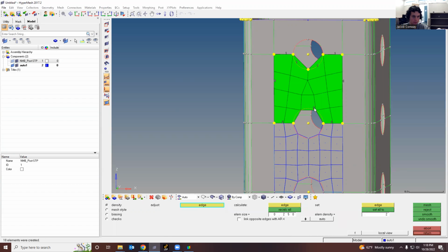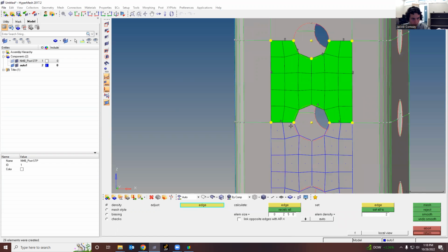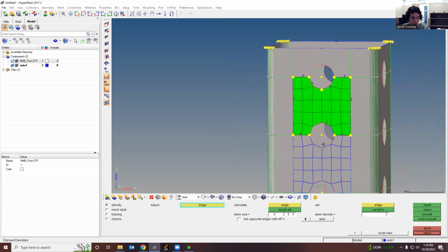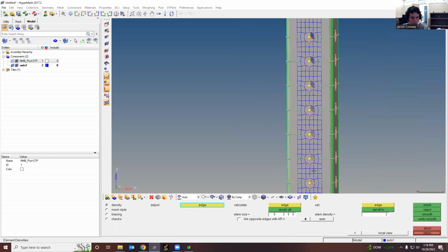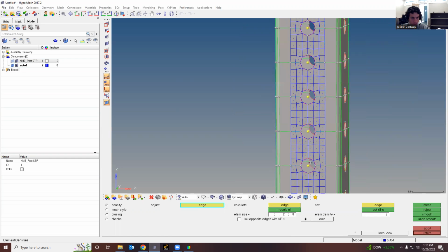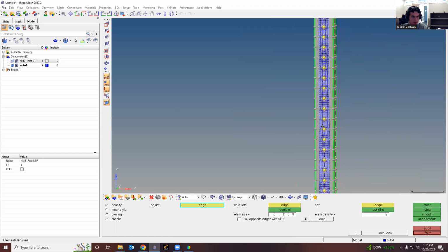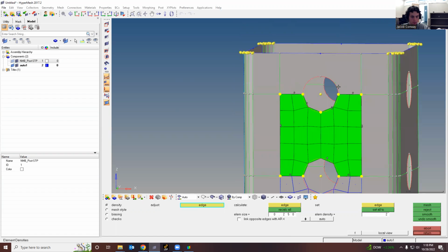So yeah, I'm actually gonna want 4 on that edge. Gonna want 2, 2, 2, 2, 5, 5. And yeah, so is there some deviance from the others on that edge? Maybe, but again, that kind of just shows that this is a puzzle. There's some troubleshooting involved along with it, but usually it's not too bad in this meshing part.